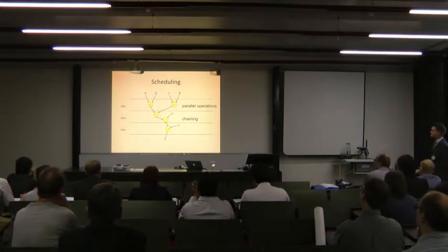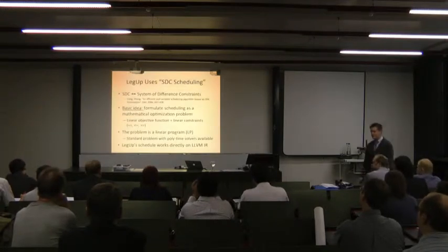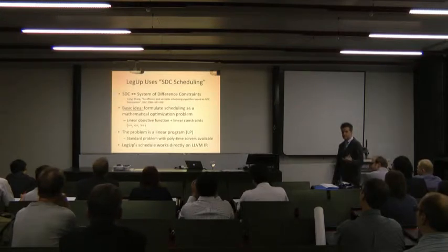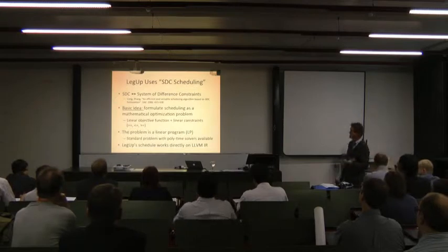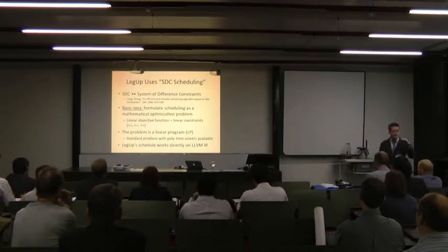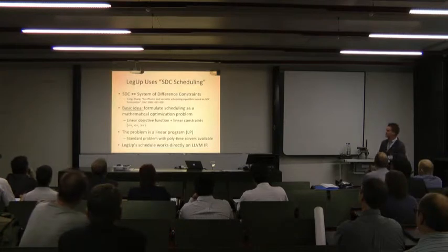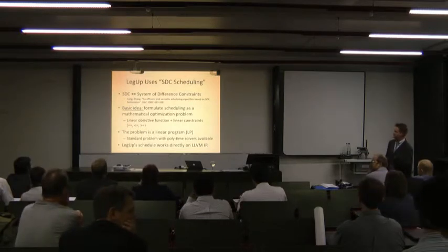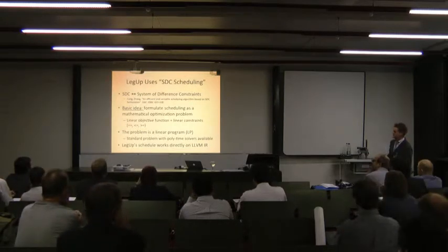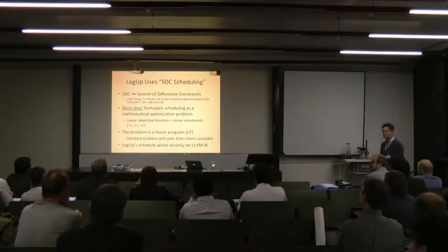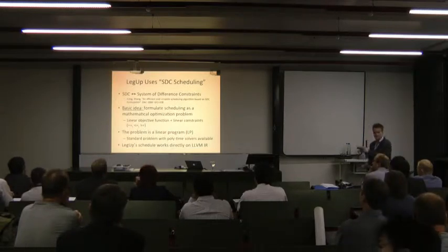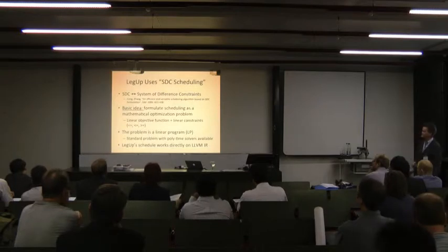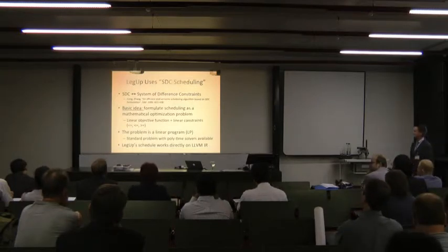That's called chaining. Now in LegUp, we use a scheduling algorithm from the literature called SDC scheduling. And basically in this form of scheduling, the scheduling problem, that is, assigning the computations to clock cycles, is formulated as a big math problem, as a linear program. Okay? And this approach for scheduling was actually published in DAC 2006. And so we formulate scheduling using this SDC scheduling, and you can go and check out that reference for exactly how that works. So we have an existing scheduling algorithm in LegUp.